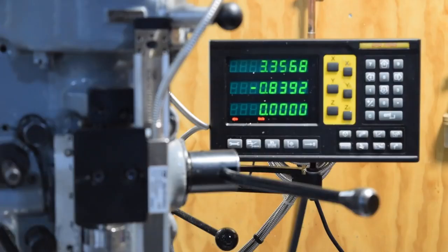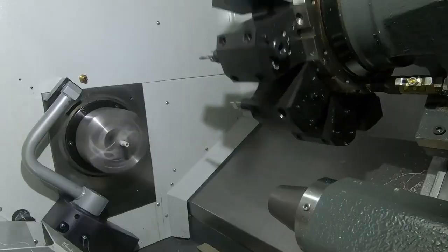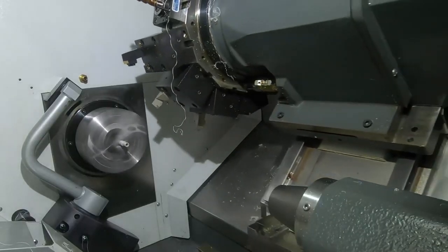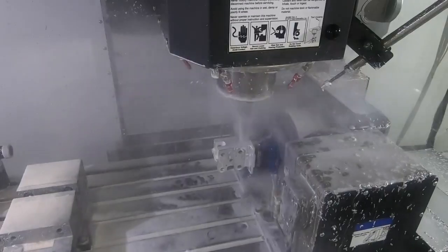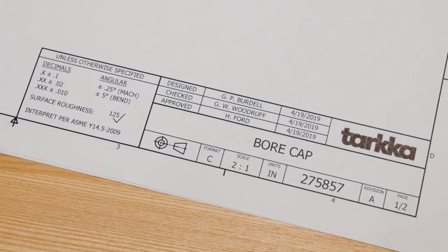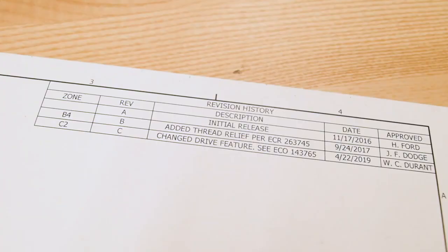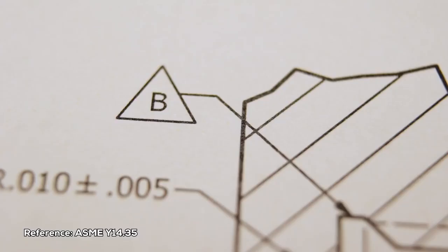A big problem we see with drawings are title block tolerances that are unreasonably tight. In the format we've provided, we tried to choose tolerances that are reasonable for most modern CNC machines, but you may want to increase these even more depending on the type of work you do. The title block on subsequent sheets of the same drawing usually contains less information and is called a continuation title block. The revision table shows when the drawing was changed, for what reason, and by whom.